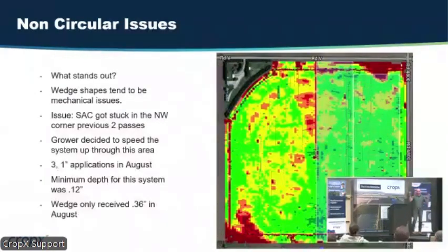Now, just a little inside information for this group, right? If you have a swing arm, you can just run it in the other direction. When you're looking at the swing arm sticking out this way, run it in this direction. It's out ahead of the pivot, so it'll get through everything dry before everything else, okay? So these are just little tidbits you guys can use, take home, and be some irrigation professionals for these guys.